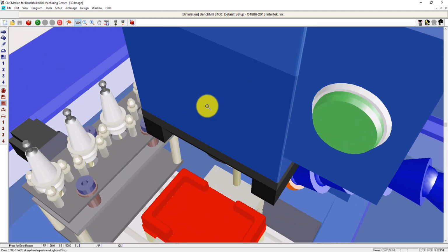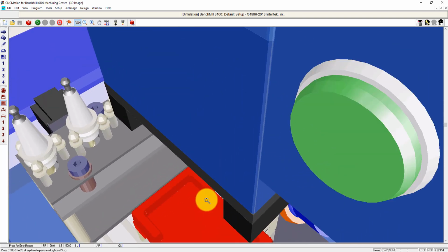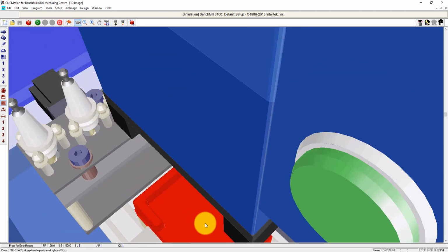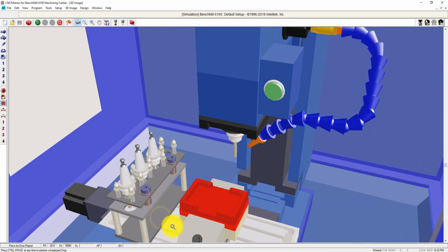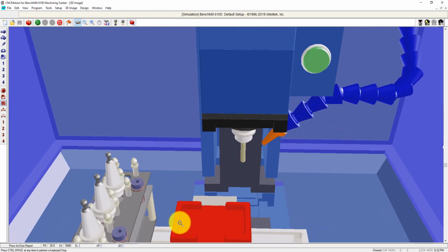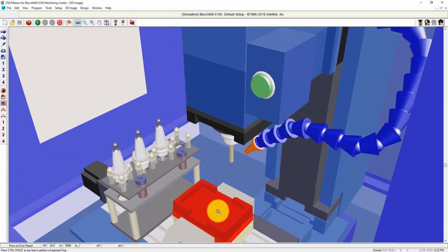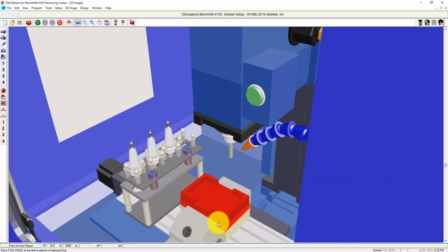Zoom in a little bit on here. It's a little hard to see, but you can see the engrave is in there, as well as the chamfering and the rounding around the outside. It did miss the vise. If we were cutting this on the actual machine, we would use a larger spacer and a smaller block. So we'd clamp on the edge of the block, and then at the end of that, we'd flip it over and face off the bottom.